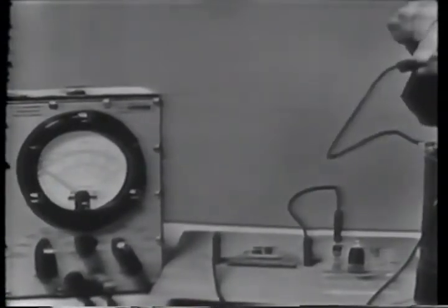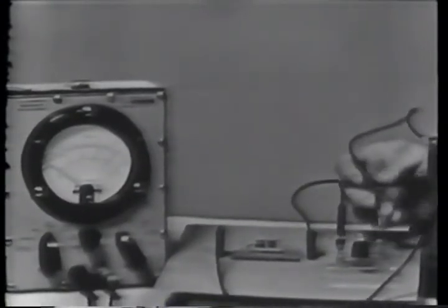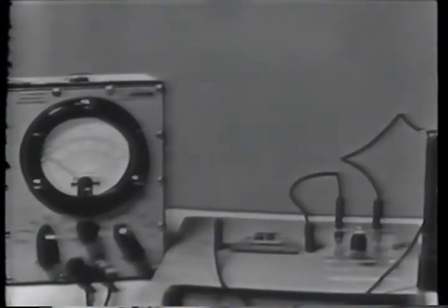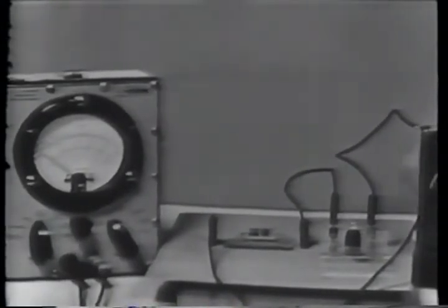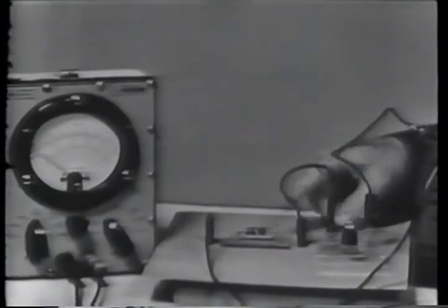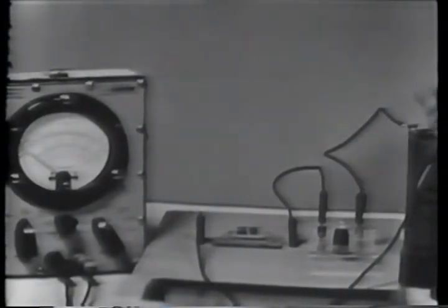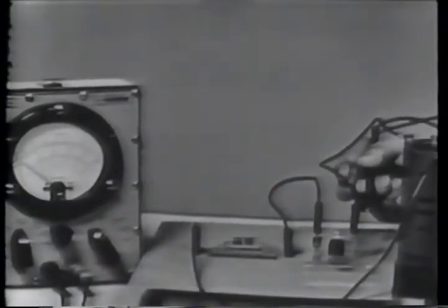When I connect the unconnected terminal of the lamp back to the other side of the batteries, the circuit is complete. Notice now, even though I have all terminals connected, the lamp does not glow. So with the voltmeter, I'll take measurements across the lamp and the resistor. You record the voltmeter indication as I go.